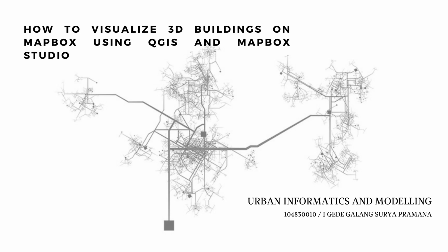Hi everyone. In this tutorial, I'll show you how to visualize 3D buildings on Mapbox using QGIS and Mapbox Studio. We'll start by downloading the right plugins, exporting building data, and finally styling it in Mapbox to create an interactive 3D map. So, let's get started.